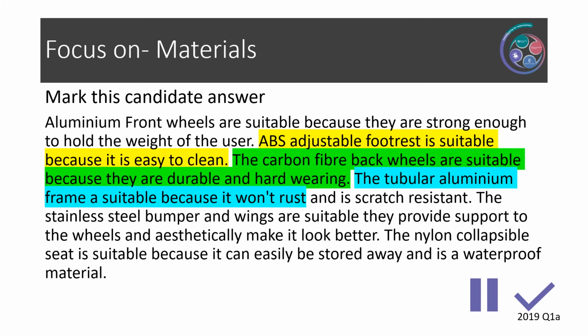Let's look at where the other answers are and explain why they are not suitable answers. The aluminium front wheels are suitable because they are strong enough to hold the weight of the user. This is not strictly true as the weight is not being distributed onto the wheels. Aluminium is also not a terribly strong material. They've also said that aluminium is scratch resistant, which is not true.